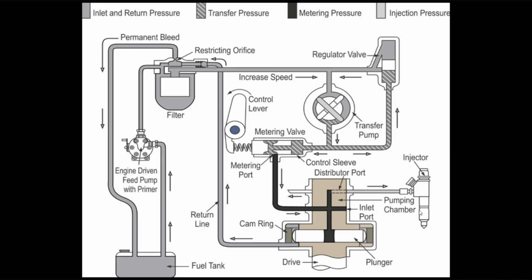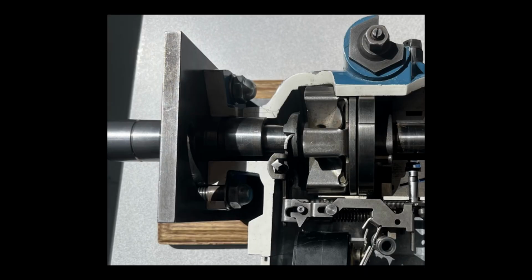After being injected, some of the remaining fuel left in the injector is returned to tank. This return line may be fitted with a restriction or orifice that aids in reducing the pressures, removing all air bubbles, and ensures smooth engine operation. That leaves us with the governor. The main purpose of the governor in this situation is to regulate RPM and power output.